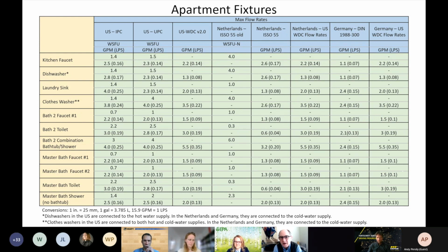And I am very confused personally about where we mean the critical pressures to be. And in the US, our fixture flow rates, our faucets and shower flow rates, are rated at 60 psi for faucets and 80 psi for showers. And given that the plumbing codes state that we're supposed to have a starting pressure no greater than 80 psi, I'm really confused how we're going to get anything close to that at any of the fixtures. Frank's shaking his head, but the answer is can't. There's always a drop in the plumbing system somewhere, right?